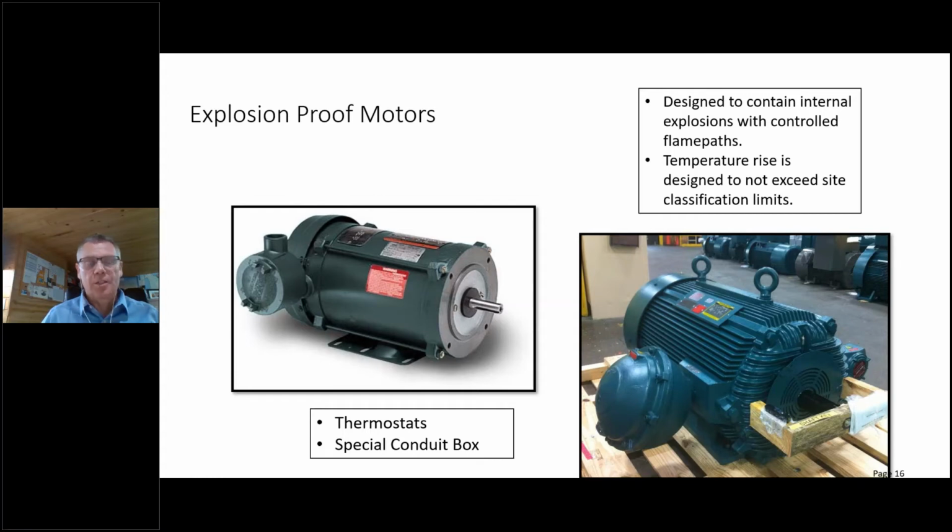And there's no such thing really as an explosion-proof motor, because when you have a rotating part moving through a hole, you cannot guarantee that some air or gas won't enter that motor, especially if it's standing still and it's self-aspirating, or pressure is at equilibrium. So the main thing here is about the size of the fits, and basically if there is a detonation, the detonation or flame is extinguished before it reaches the outside atmosphere.